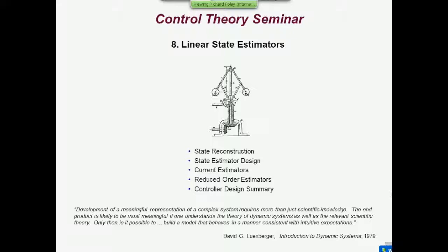And it gives you generally a good performance, but one which you can improve upon by using the most recent measurement to produce the state vector in the same sample period, and that is called a current estimator. Unfortunately, the name rather implies that you are estimating electrical current, which you're not. You're using the current output in the estimator algorithm. So that's one way in which the basic estimator design can be improved.